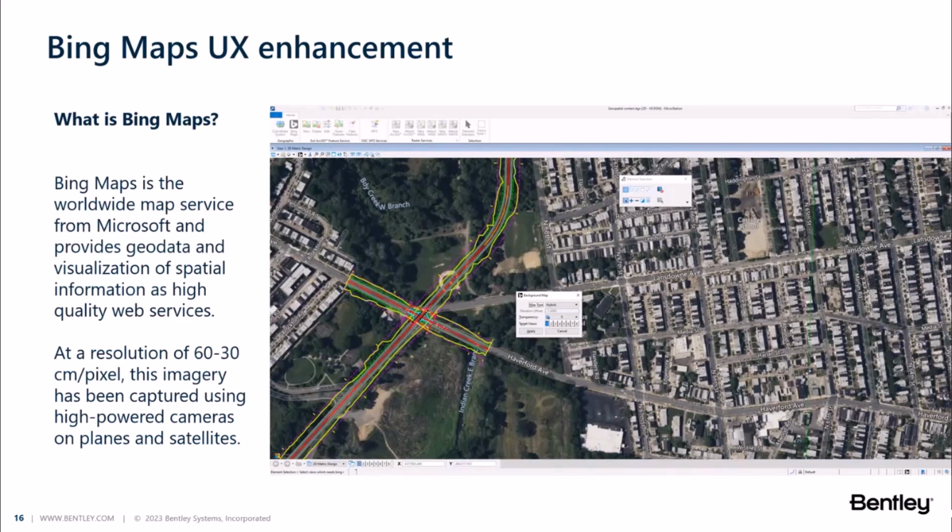Then we take GNSS or GPS coordinates and transpose them into a DGN file while setting the geographical coordinate system in that DGN file to create the relevant templates for the design to commence. And then we cross-reference that with the survey report that should have been produced, to ensure that all the checks and assurances are done prior to any design taking place. Okay, understood.